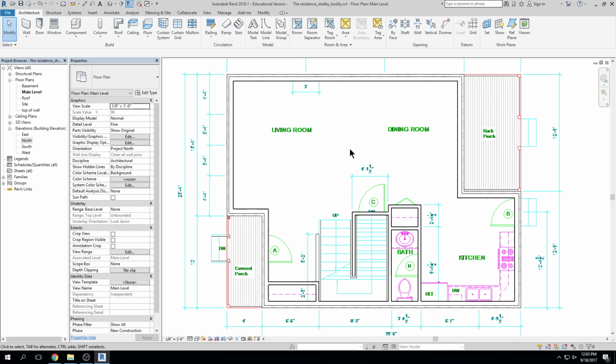So not only do structural grids show lines of structure in projects, but secondarily, they allow you to locate things in projects, right? So if you're talking to one of your structural engineers and you say, the column in the living room is in the way. And they say, well, what column? There's two of them. And you're like, oh, the top leftish one. It's not very accurate, right? Then they interpret top leftish as bottom leftish, rightish, middle, and they move the wrong column. So what's nice about grids is that you can say at grid intersection A4, that column, can you please move it? So it gives you a little bit more definition to what you're talking about, okay?